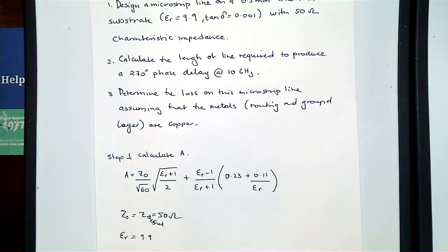Or, for example, in a particular case that I was talking about, Will, where we're designing 60 gigahertz chipsets, and we're doing phased arrays on these chipsets for VR applications. You want to be able to have a sequence of antennas and phase the antennas relative to each other, so you can form a very narrow beam in order to do beam forming. You can use this technique, switching particular lengths of line in order to get the relative phase change, right?